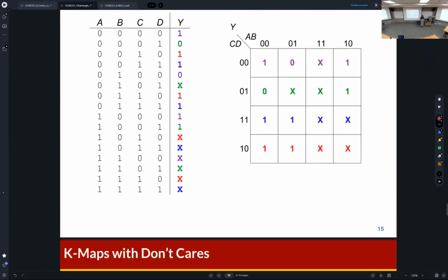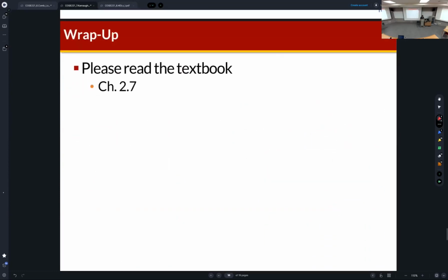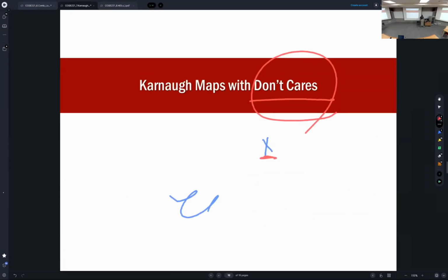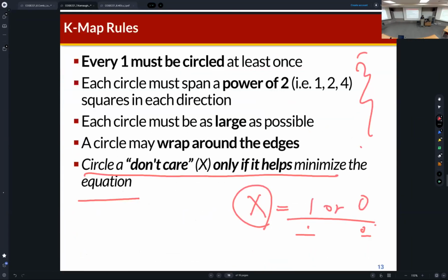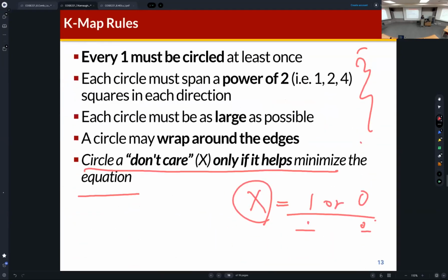So this is the end of the Karnaugh map. Okay. So please read the textbook. Just to remember that using the Karnaugh map, we can optimize the Boolean equations easily. Okay. So the Karnaugh map is the graphical method for optimizing Boolean equations. But also you need to remember the order of signals like 0, 0, 0, 1, 1, 1, 1, 0. Okay, this is very important. Also, you need to remember these grouping rules. Okay, so if you follow these rules, then you can easily optimize the Boolean equation. Okay.